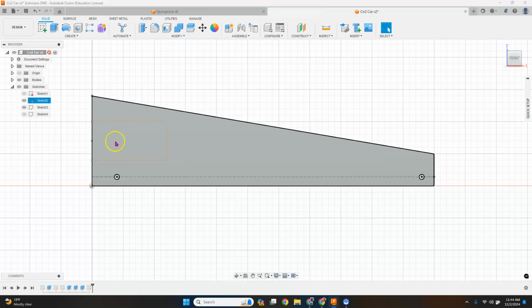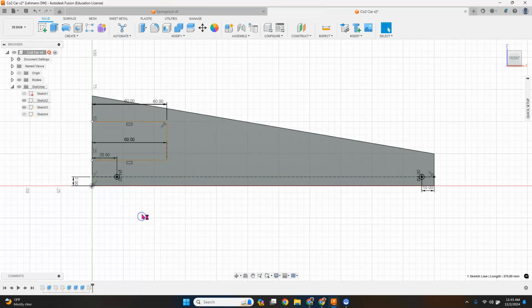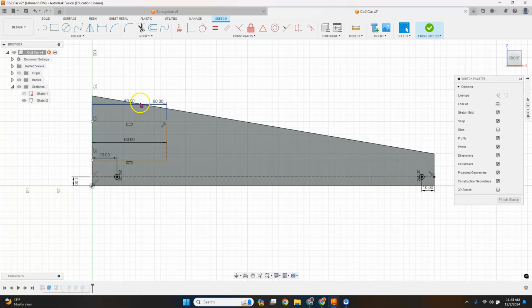Now, what we want to do here is we want to come in and we want to right click, and honestly, we're just editing that same sketch. So if you've been in that same sketch that we were just in, you can move these guidelines around by selecting them and kind of dragging them where they need to go. Apparently I have 2. I might have done that twice in the last thing. You can also delete them if you don't want them there. All right, selecting and deleting should allow it to go away.